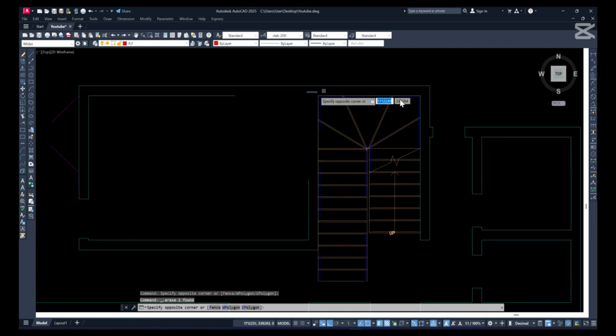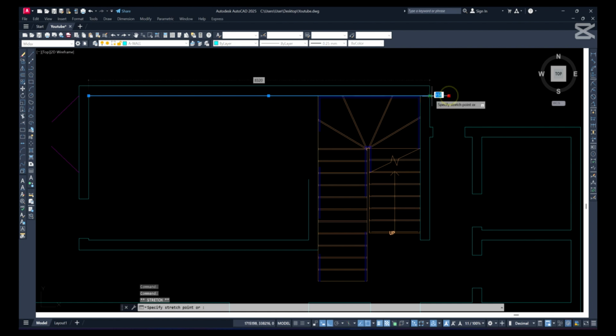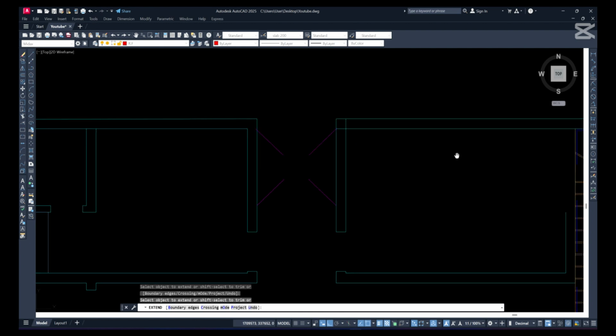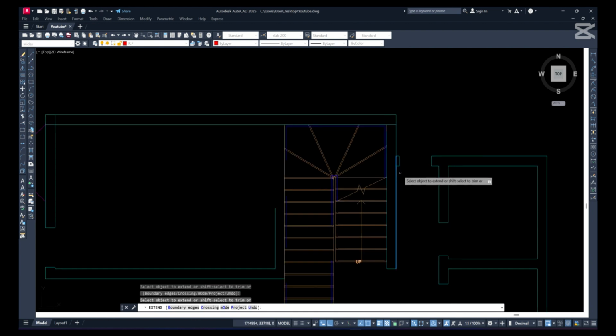So there are different ways to go about this. Even if the panel is more than that, maybe let's say 6 meters by 6 meters, we can introduce what we call hidden beams. Some people call them flat beams, and increase the reinforcement spacing just to give the slab more strength. So this is not something one should be worried about. Most people get worried when they start seeing a 6 meter span, they start panicking like, oh, how is this going to work?